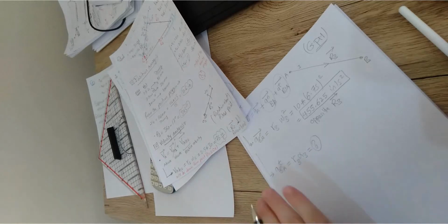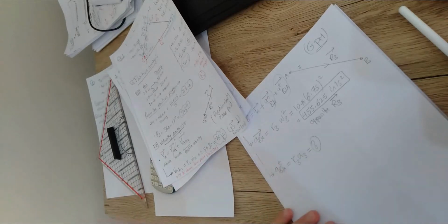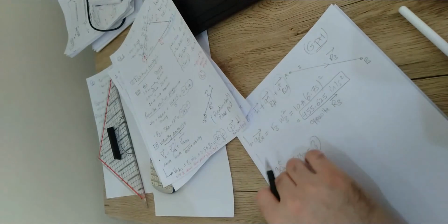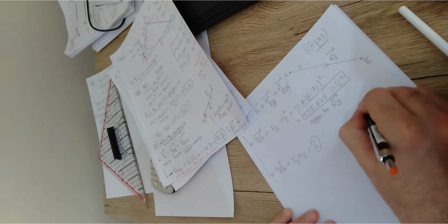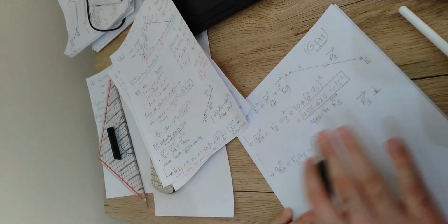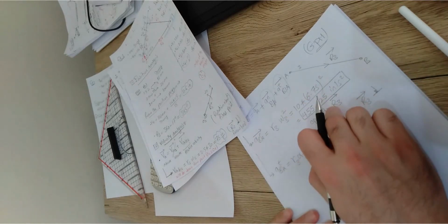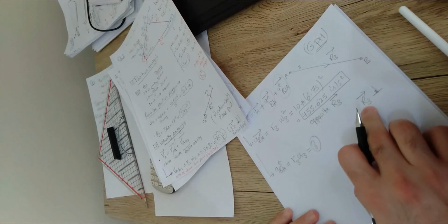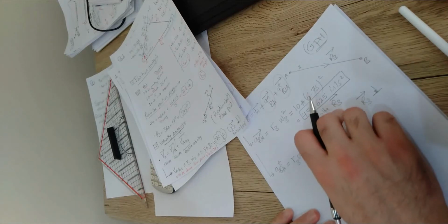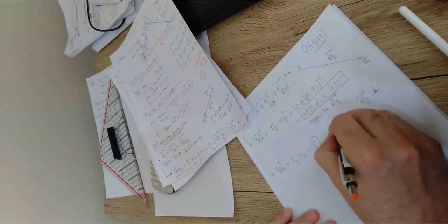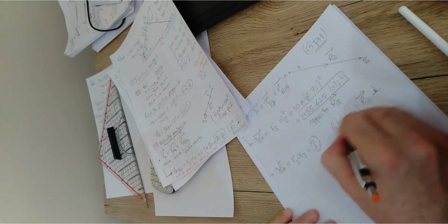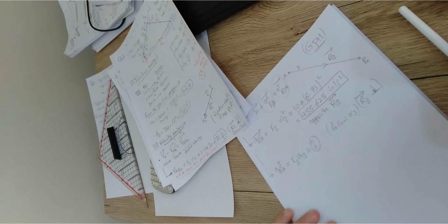Make sense? So the tangential component is unknown in terms of magnitude, but we have an indication about its direction. It should be perpendicular to the R3 vector, or in general perpendicular to the A normal, which is automatically perpendicular to R3, since A normal is opposite to R3, and it should follow alpha 3, which is unknown.